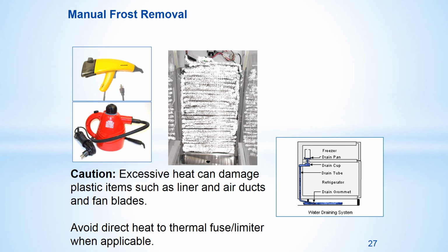Also remember that thermal fuses are generally set to blow in the area of around 140 to 160 degrees. So what temperature is steam? Well, typically it's 212 degrees Fahrenheit. So keep your steam from directly hitting the limiting device. Otherwise, you might be replacing that as well.